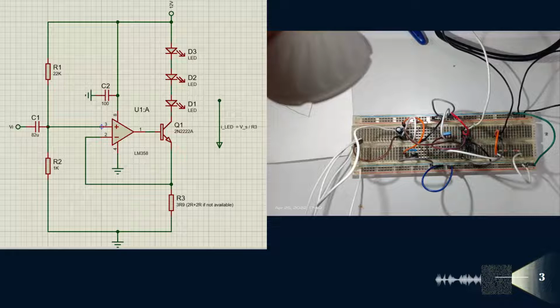We have to keep in mind to set a lower value such that V bias is slightly higher than 0.5 volt. If it was somewhat below 0.5 volt, the audio signal, or VI, would clip off below its maximum negative value. The appropriate range of a resistor value should be large enough to limit the power dissipation and small enough in comparison with the internal input resistance of the op-amp. Plus, if the resistor value is not negligible compared to the input resistance, the op-amp can no longer be assumed as ideal, resulting in faulty operations for op-amps such as the LM358, which are built with BJTs.